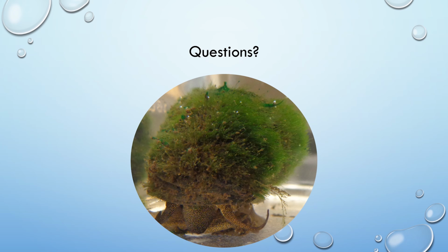Generally, water 1 or 2 feet above the sediment top layer is what we want to look at when we do water quality analysis, especially in these situations. So the top water of your pond is probably going to be always very low in nutrients, just because there's a lot of organisms using up a lot of those nutrients, and unless you have a huge amount of incoming nutrients, most of the nutrients in the water column is going to eventually come up from the bottom in the sediment layers.